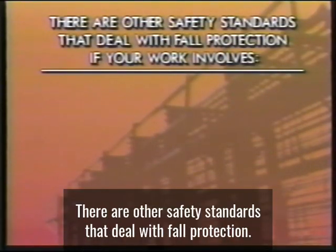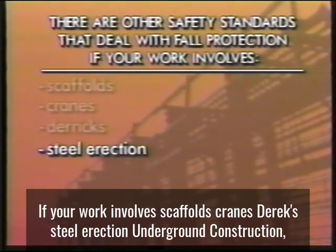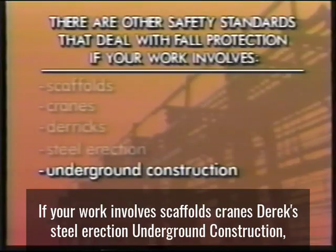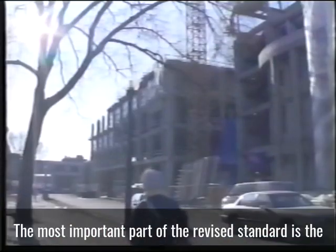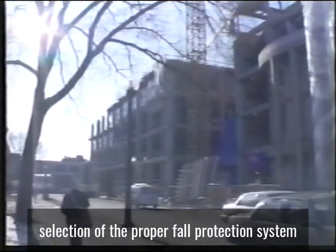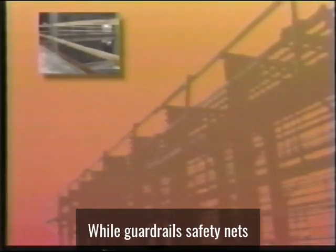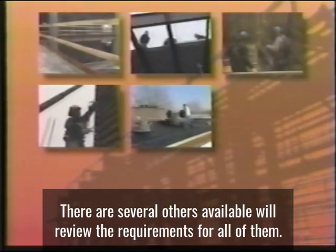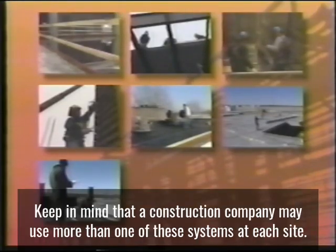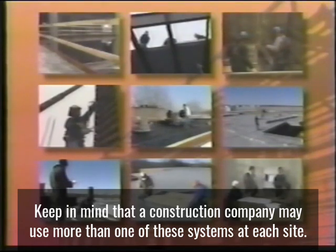There are other safety standards that deal with fall protection if your work involves scaffolds, cranes, derricks, steel erection, underground construction, power transmission and distribution, stairways, or ladders. The most important part of the revised standard is the selection of the proper fall protection system for a construction site. While guardrails, safety nets, or personal fall arrest systems are the most conventional fall protection devices, there are several others available. We'll review the requirements for all of them. Keep in mind that a construction company may use more than one of these systems at each site.